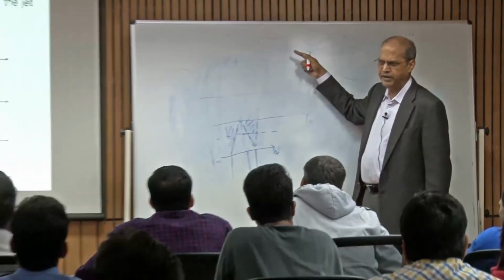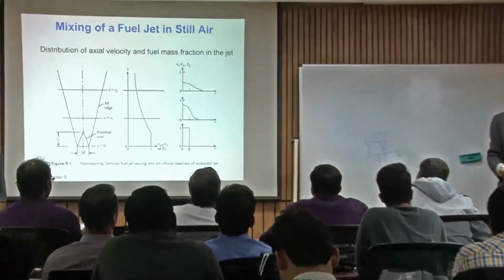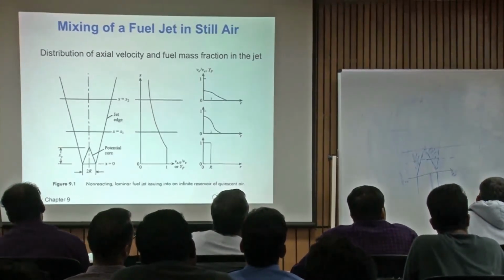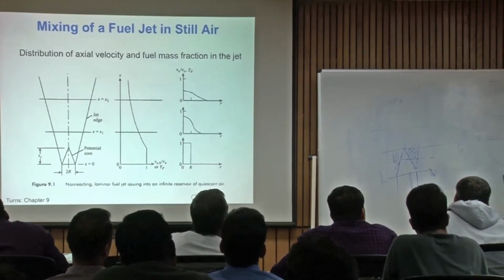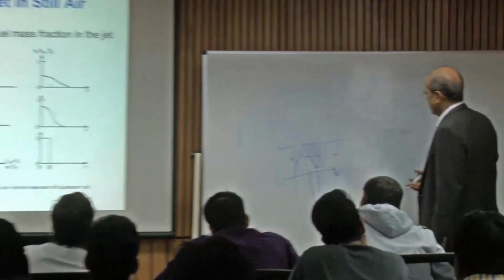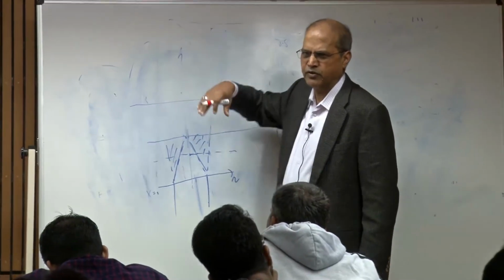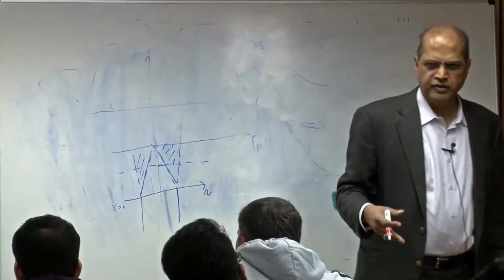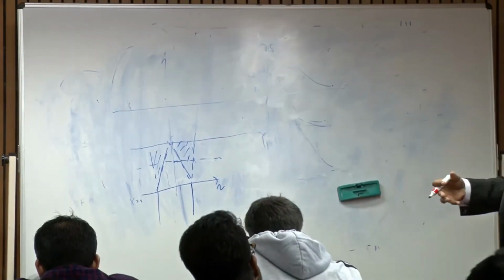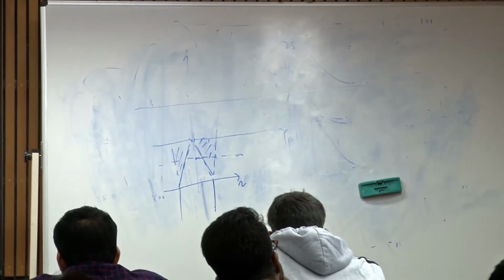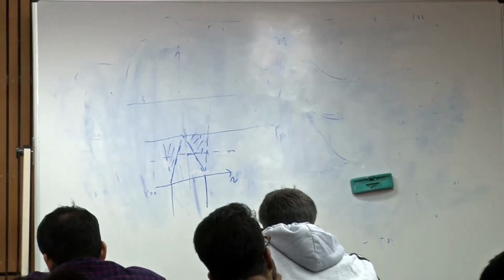For example, for a methane flame, the stoichiometric value of Y_F is about 0.055. You can imagine that this will determine the flame length, where Y_F is close to 0.055, because the flame surface corresponds to the stoichiometric mixture.